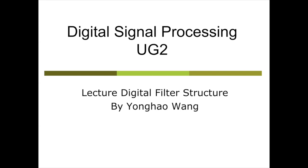It is one of the, I think, three most important aspects of DSP for audio processing. I normally name these three aspects. The first is convolution. Well, actually, convolution is one type of filter, but I single it out because it's important to reflect some natural acoustical properties. Like when you clap your hands in a room, you have some reverberation, and you can use that as an audio effect in a digital way. Okay, convolution.